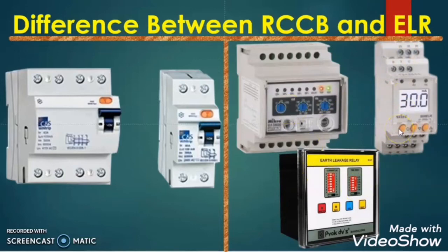But that is wrong. Both RCCB and ELR are used to protect humans from electrical shock which can be due to the earth leakage current. The ELR has no role to protect the electrical installation.